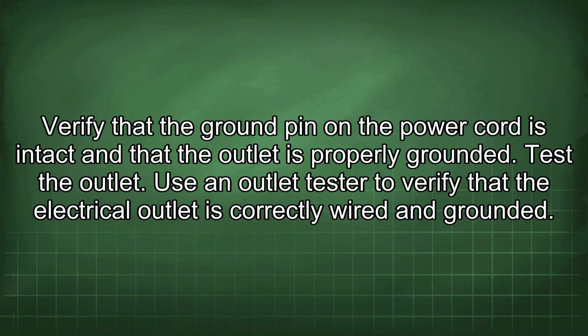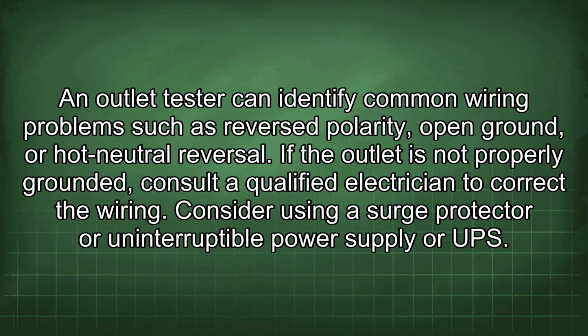Test the outlet. Use an outlet tester to verify that the electrical outlet is correctly wired and grounded. An outlet tester can identify common wiring problems such as reverse polarity, open ground, or hot neutral reversal. If the outlet is not properly grounded, consult a qualified electrician to correct the wiring.